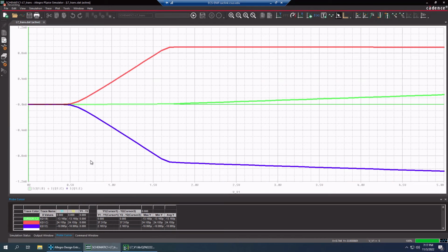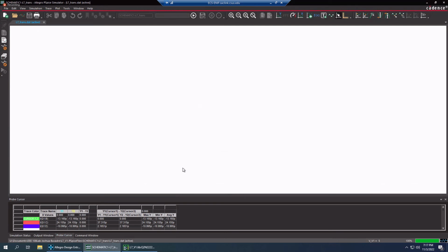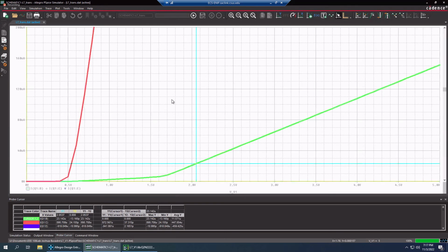But I think if we were to explode that, let's right click on the left for a moment. Instead of going from 1.2, let's go from minus 0.4, or let's go from 0. Yeah, make that 0, and let's take it to 0.2. Okay, let's see what that looks like. Again, it's just microamps controlling that and switching that transition.